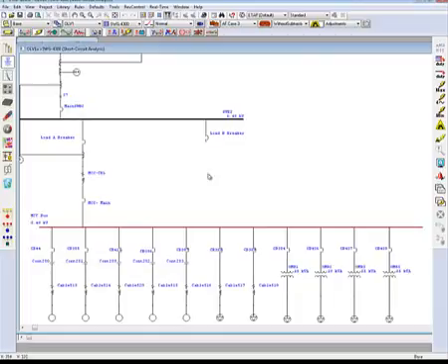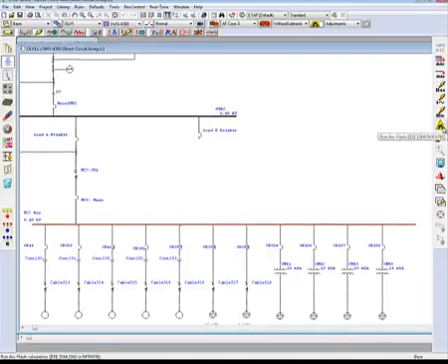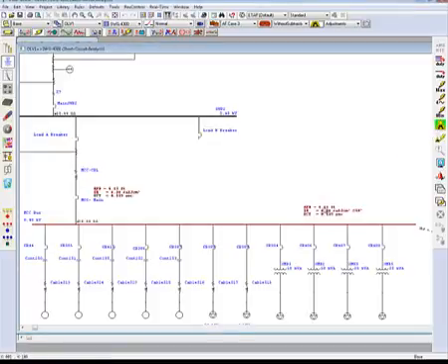So here we have a low voltage 480 volt MCC bus. We'll go ahead and run an arc flash analysis, the classical method of just running the triangle with an arc flash. So the results are shown and the device is operating at 135 milliseconds. Everything seems okay. Let's go ahead and confirm the operation of the device by running a sequence of operation.